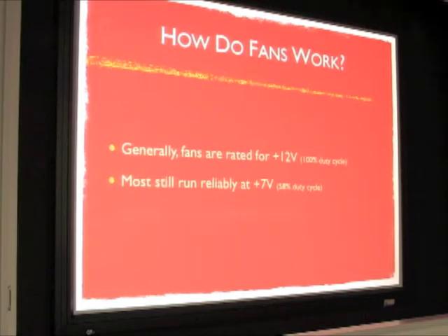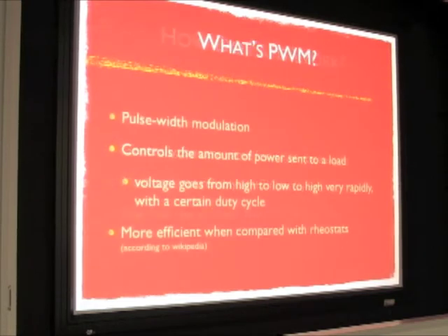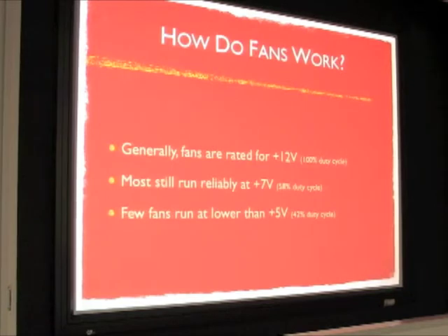And few fans run at lower than 5 volts. So if you supply less than 5 volts to the fan, then it's not likely to start at all, and it's not likely to run at all. So you have to ensure that you supply at least 5 volts to the fan if you want it to run reliably.